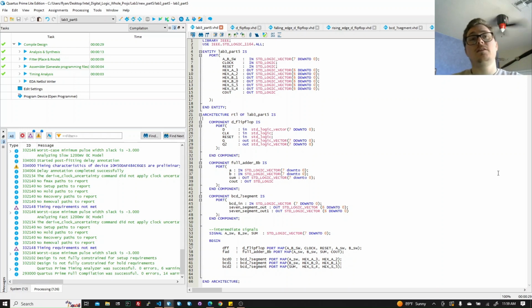And in this part, we need to build a circuit that displays inputs and outputs to the 7-segment display. Specifically, we needed to have two 8-bit inputs, A and B respectively, show up on 4 7-segment displays in total. But because they're 8 bits, we can't use two simultaneous inputs because we only have 10 switches on our DE10 light board. And so we had to come up with a way to accept the input for A, then accept the input for B, and then we needed to add those together and display that sum on the remaining two